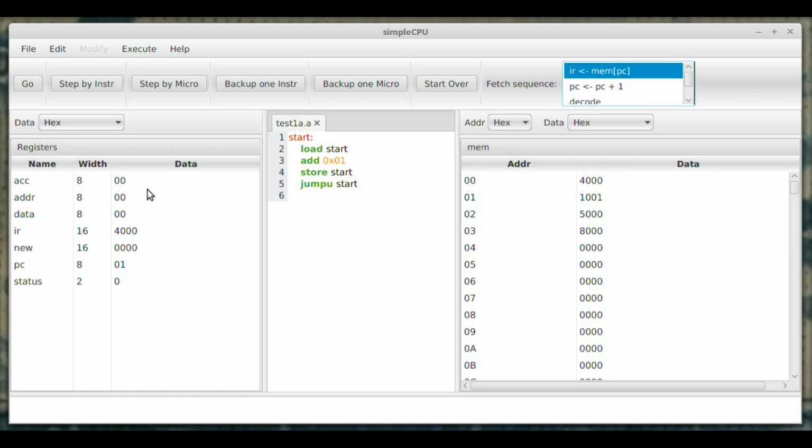After we've executed the first instruction, nothing really changes, other than the accumulator being updated with the value 0, because it loads the low byte at address 0, and the low byte at address 0 is the value 0. Then I perform the add instruction, so I'll add 1 to the accumulator, and now I will store the result 1 out to memory at address 0, overwriting the load instruction. And as we saw in the previous example, when I write that value out, the high byte will be zeroed. So now that bit pattern has been changed.